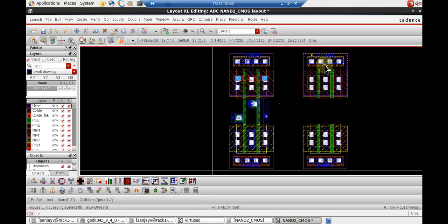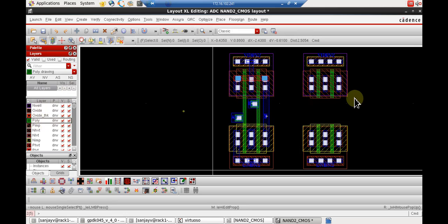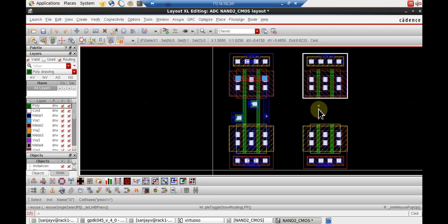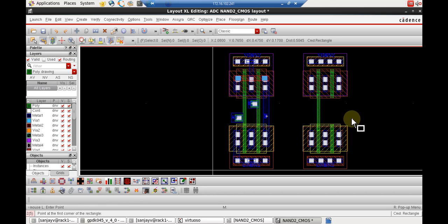So that is the only difference. Having made this, now the problem is to connect these two gates. So this is A input and the B input. So I have used a poly. There is a poly option available here, and then I created a rectangle out here. The shortcut for rectangle is R, and then I created a poly. So I can create a poly link out here.